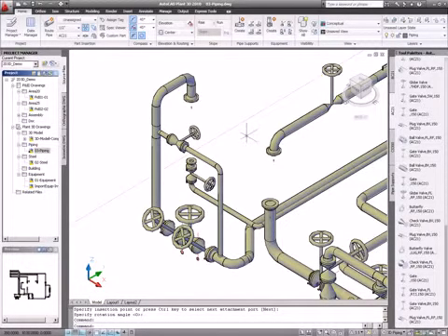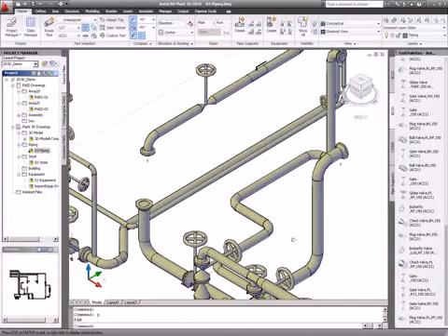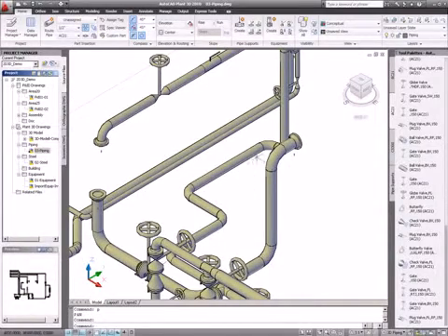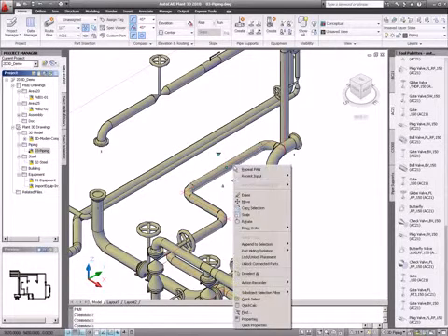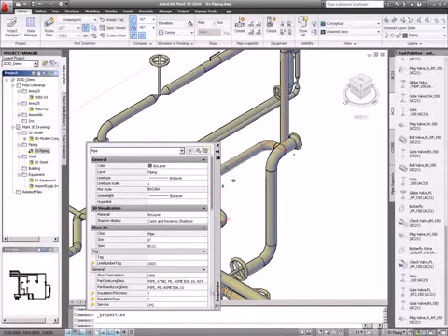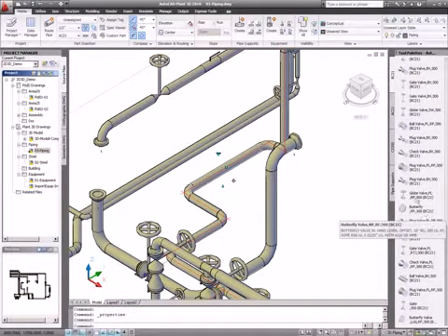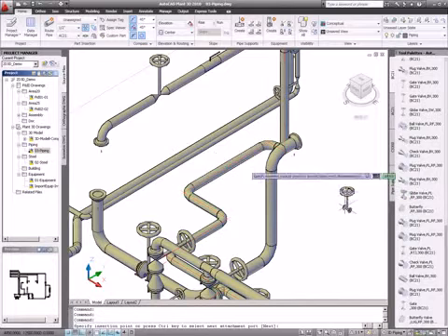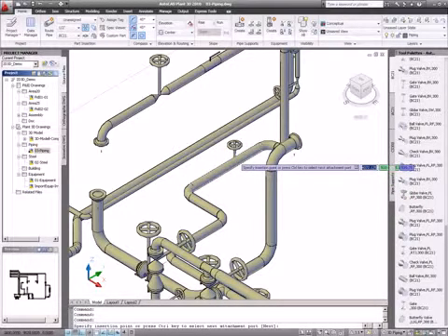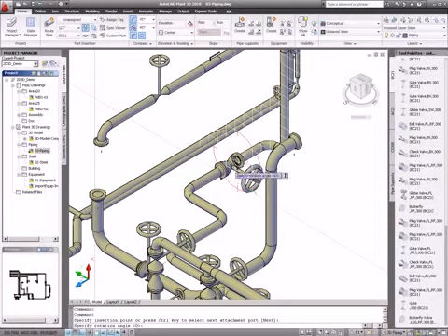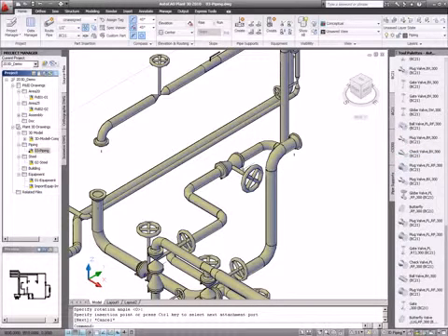You can also again start with a pipe on another pipe. So if I then want to insert something on this pipe, I can select the valve. In this case, if you take a look at it, I'm not sure what kind of dimension or whatever, it's a BC21 and that's 6-inch, okay. Then I select the BC21, find the valve I want to use, select it, select the pipe, and there you go. And then give it rotation for your top works. It's also very easy to change.